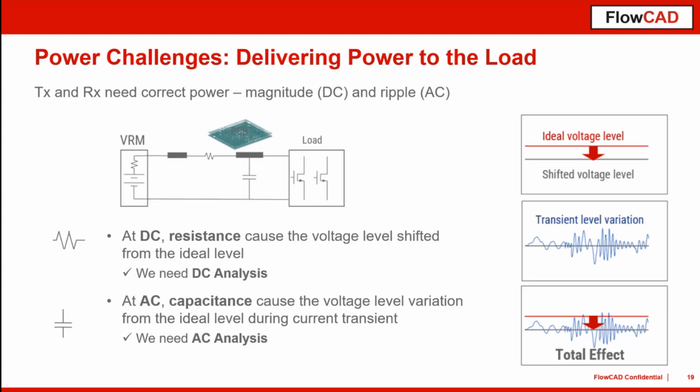devices. And in addition, we also have to cover so-called AC effects. That means we also have to cover some parasitics in your design, creating some noise on your power delivery systems. The root cause can be different, but in this case we have the possibility to analyze the distance from your decoupling capacitors to the supply pins of your voltage regulator. And we need these decoupling capacitors to reduce this noise. And this is a very, very easy way to find how we can do that.